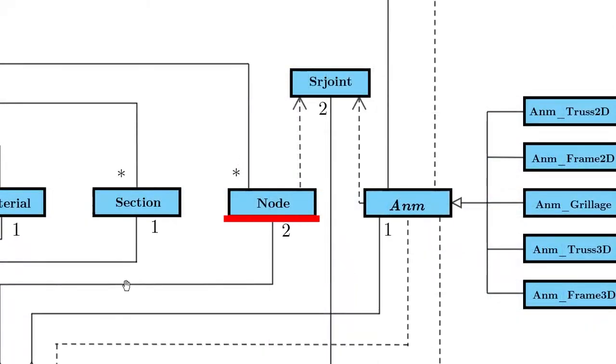The node class is a class that defines node objects in the program. A node is a joint between 2 or more elements or any element end. Use it to discretize the model. It's always considered as a 3-dimensional entity, which may have applied loads or prescribed displacement.